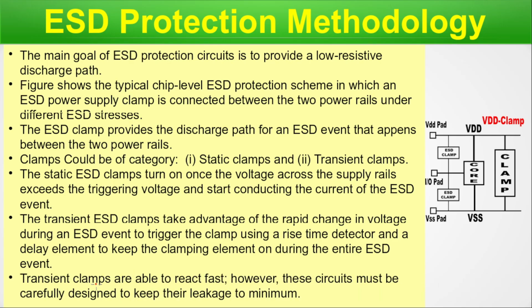Transient clamps are able to react fast. However, these circuits must be carefully designed to keep their leakage to a minimum. So this is another design need because most of the devices now are battery operated, so the leakage should be minimum. That is our expectation. So here we talked about the ESD protection methodology, specifically static clamps and transient clamps. Let's move on to the next slide.